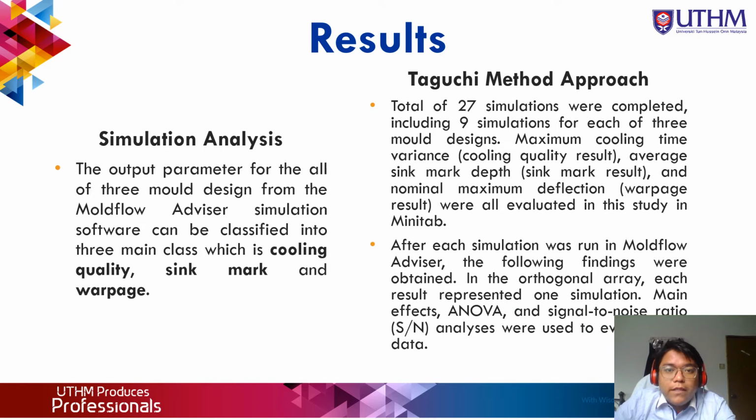Okay, for the next is the results. Results are divided into two. The first one is the simulation analysis, and the second one is the Taguchi method approach. For the simulation analysis, the output parameter for all of three design from the Moldflow Advisor simulation software can be classified into three main classes, which is the first one is the cooling quality, the second one is the sigma, and the third one is the warpage.